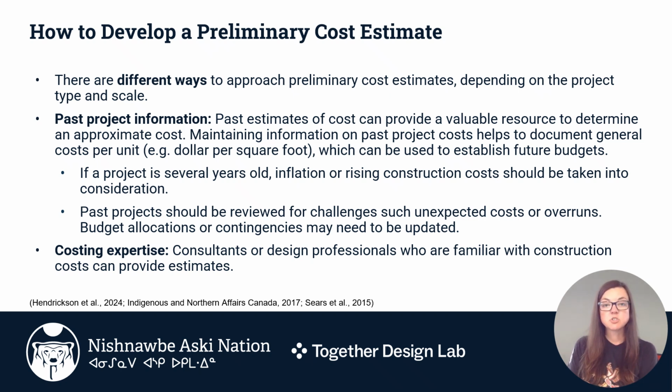If a project is several years old, inflation or rising construction costs should be taken into consideration. Past projects should be reviewed for challenges such as unexpected cost or overruns. Budget allocations or contingencies may need to be updated. Consultants or design professionals who are familiar with construction costs can provide estimates. However, one of the best ways to estimate cost is to look at past project information.